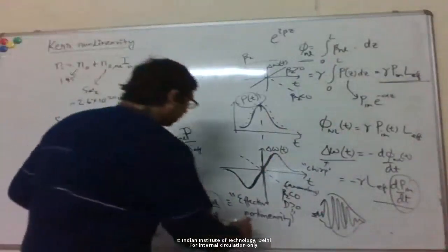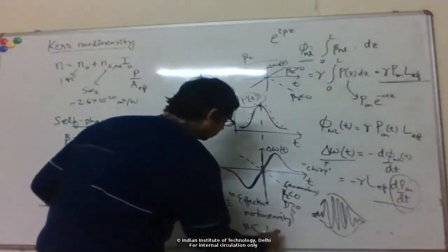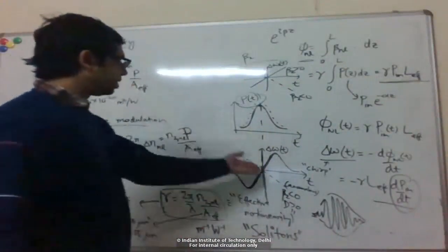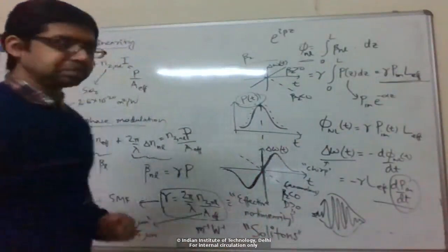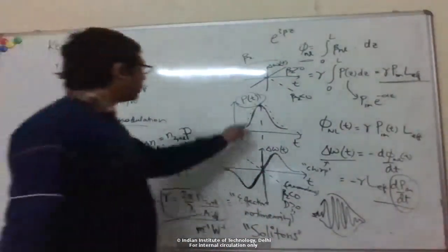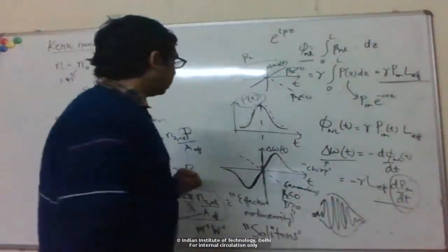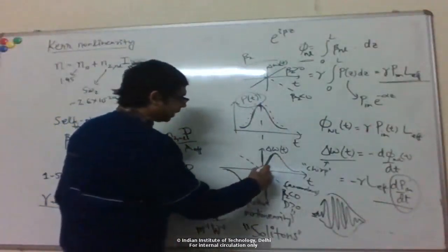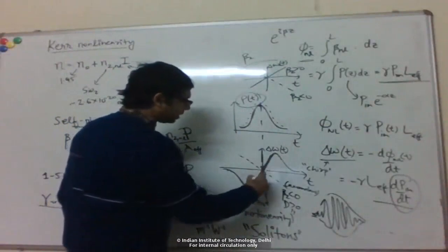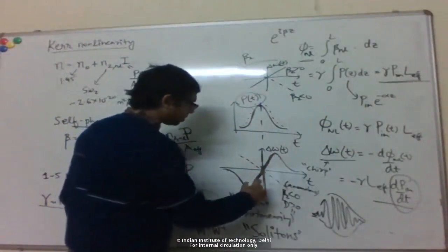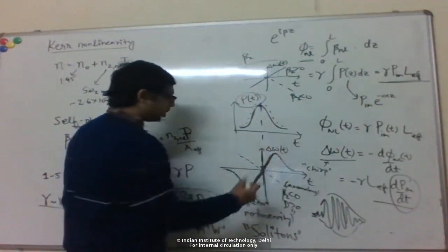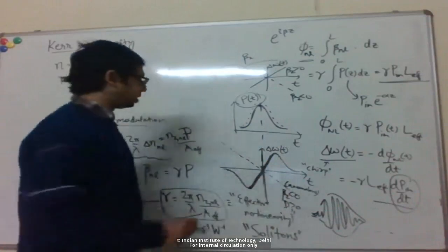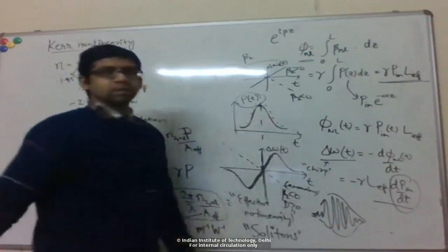Such pulses are known as solitons, where the dispersive chirp and the nonlinear chirp cancel each other out. You can see that this will happen only at a very particular power. Not only that, you can see that the nonlinear chirp is only linear in this middle region, and beyond that it goes nonlinear, whereas the dispersive chirp is always linear. This is for the Gaussian pulse case.